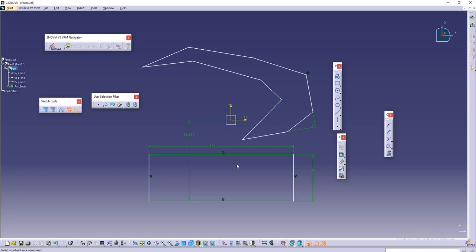Now this part is missing, this is showing white, right? So I can go back and click anywhere. If the horizontal is this, you have to consider the x and y axis all the time for creating the constraint. So here we have used horizontal to horizontal, and then we will use vertical to vertical, right? How much is this? Now it is showing green.